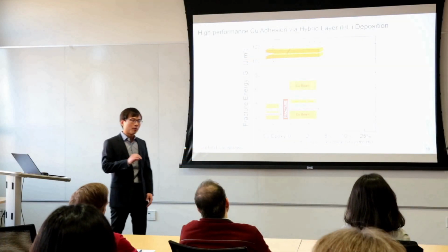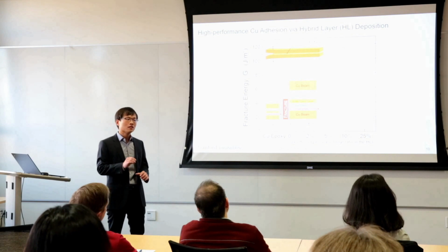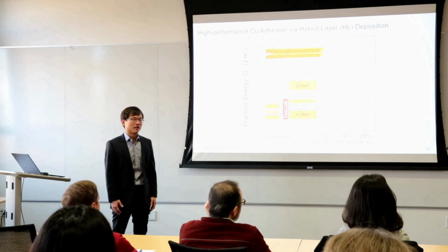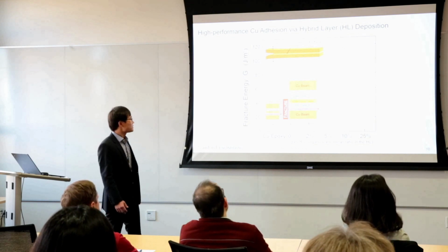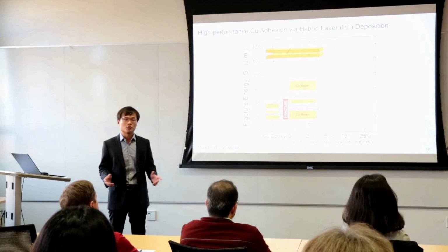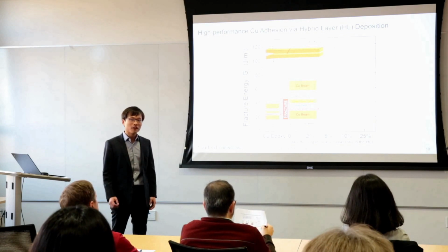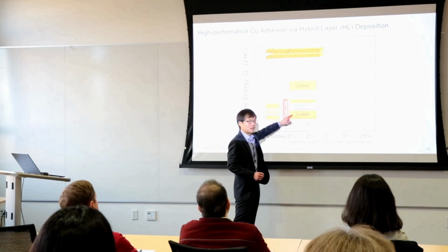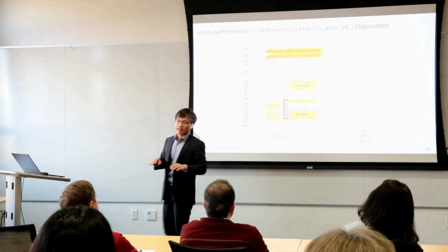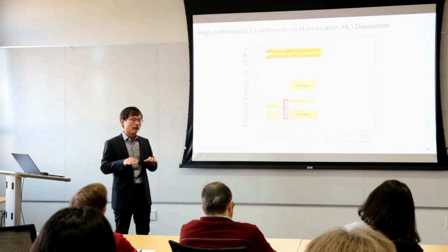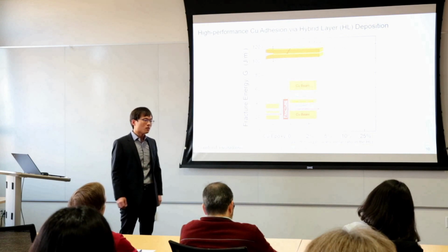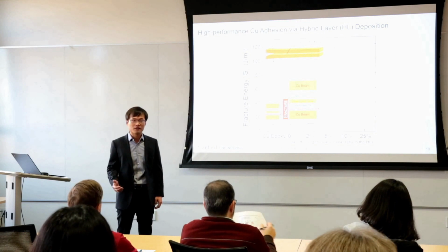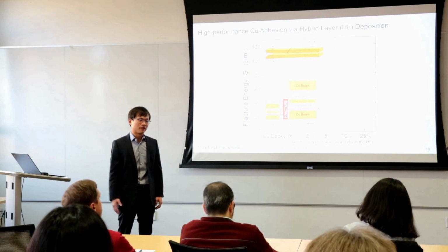And if we now apply our hybrid film but containing no or a very small amount of the organosil that we had been talking about, we see a similar fracture energy of only 10 joules per meter squared. And the failure still occurs near the copper surface, in between the hybrid layer and the copper beam, which is again within the weak copper oxide layer. Now, what would happen when we incorporate the organosil into our hybrid layer composition?